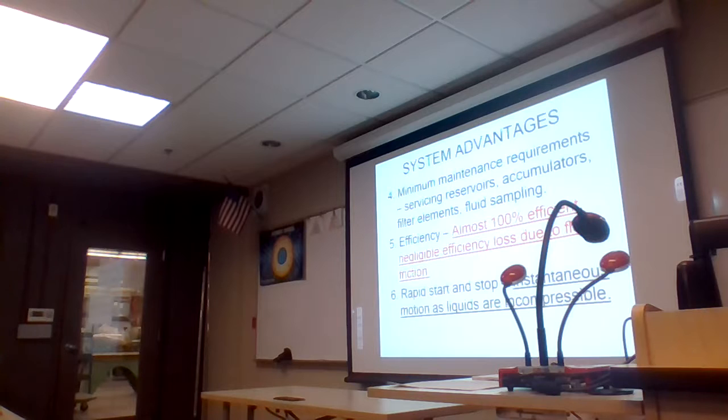I added this in here, rapid start and stop. When we have hydraulic motors that give you rotary motion, as soon as you apply hydraulic pressure, that motor starts right now, like a cooling fan. And the same thing is true: there's usually no coast down. Once you cut the hydraulic flow to it, the motor stops almost instantly. This is because of the incompressibility feature of hydraulic fluid. Liquids are considered to be incompressible. You can't really change their volume by applying additional force to a confined liquid. This is not true of gases. Gases are compressible, but hydraulic fluids are considered to be incompressible.